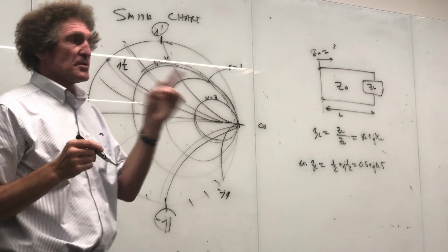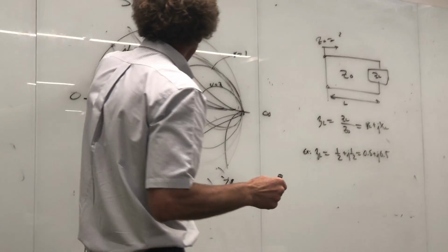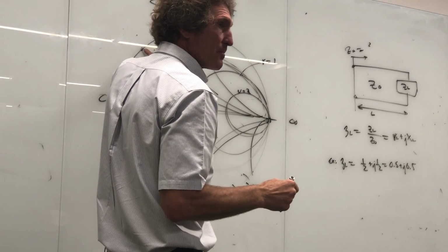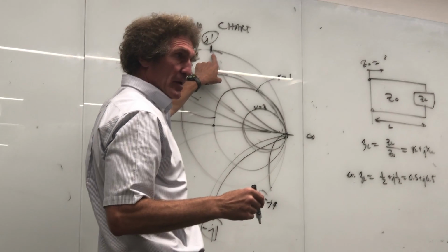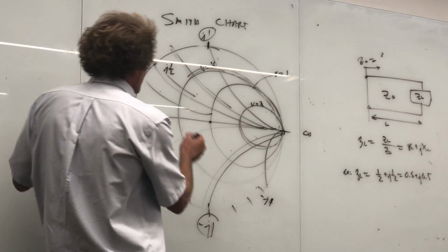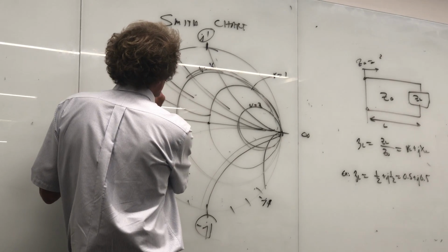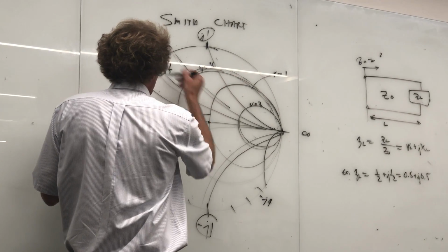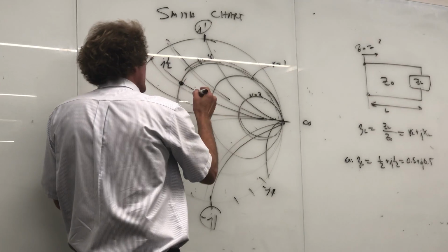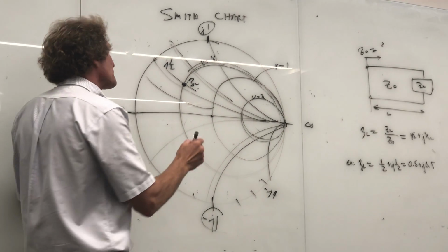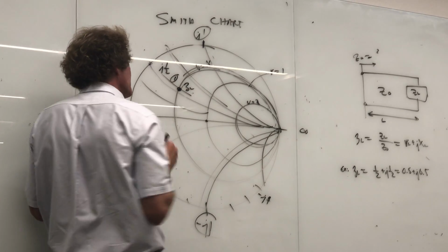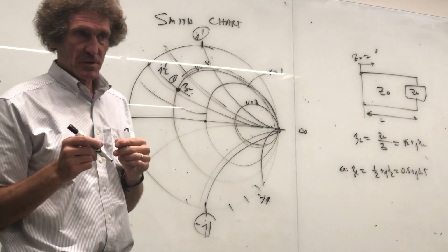If you have a Smith chart, can you see how in the outer part you'll see something on the ledger that will have 1/2 on it? And you see this one is 1. Take a look up here. All right. So you find that half one, and then you go to the point where they intersect. So this intersects that, as I'm showing you right here, and that was the Z load. And the very first point you always put is the entry point, and label that 1 with a Smith chart.